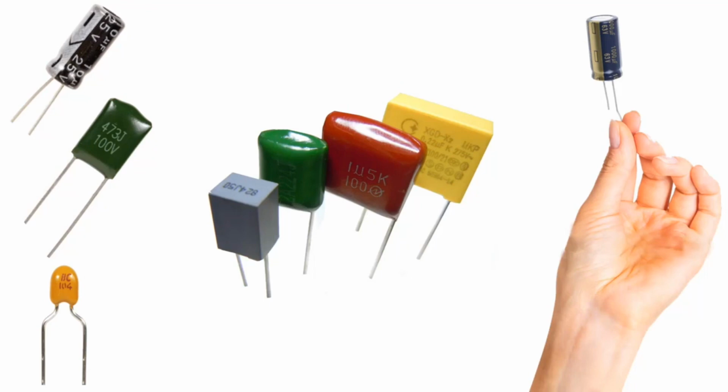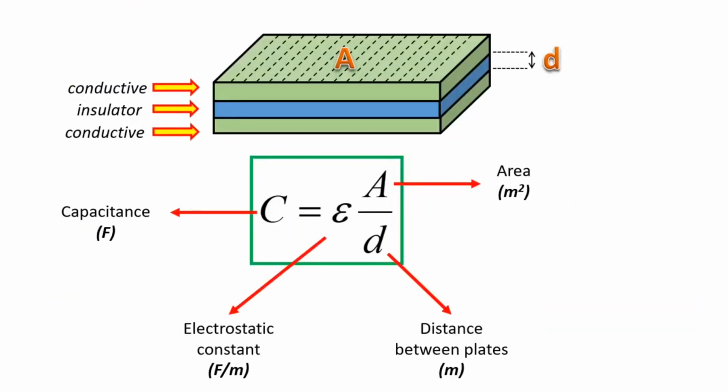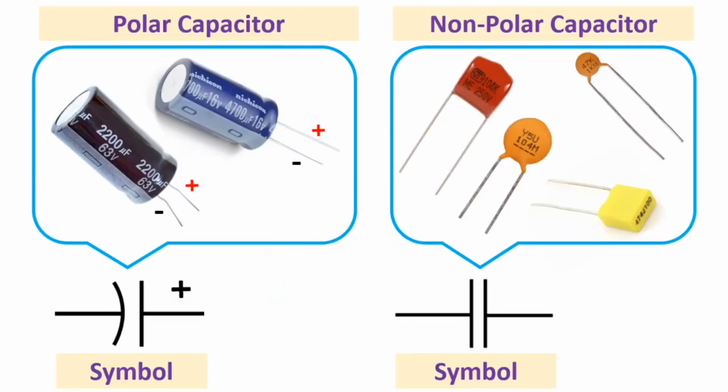The values that you will typically encounter in most capacitors are measured in picofarad, or pF, nanofarad, or nF, and microfarad, or uF. These are often used interchangeably, and it helps to have a conversion chart at hand. Electrolytic capacitors are typically polarized. This means that one pin needs to be connected to the ground side of the circuit, and the other pin must be connected to power. If it is connected backwards, it won't work correctly.